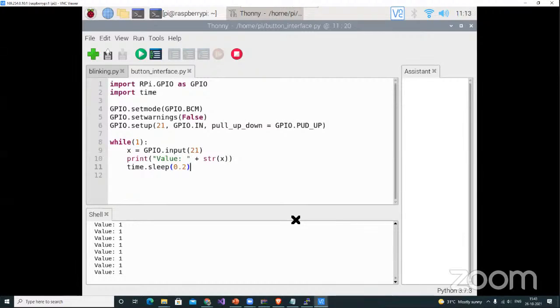So this is the actual push button. It is quite different, not general purpose, it is an industrial grade button. I'm just going to press this. Here you can see, whenever I press this button, it is pulled to low. Otherwise it stays pulled up because I have used an internal pull-up resistor to avoid the pin floating. Just press the button.